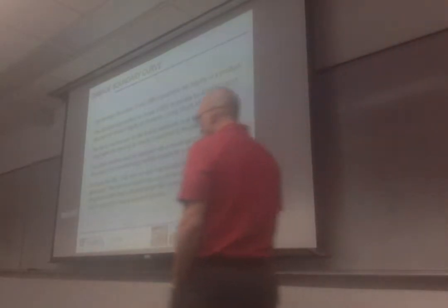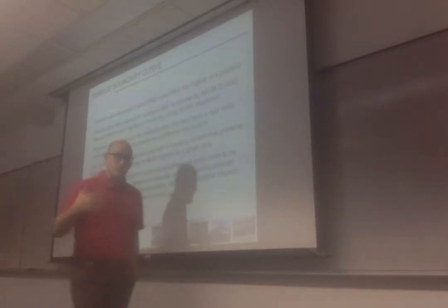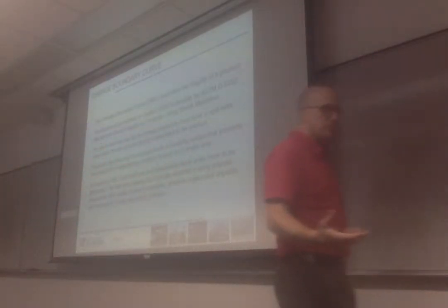I'm not talking about a packaged product. I'm talking about a product itself. So to be able to design a package to protect the product during shipment and distribution, you need to know its fragility. So obviously we need to know some of its characteristics. We already talked about this previously. That's why we talked about vibration and we looked at finding natural frequencies of a product that can cause problems.